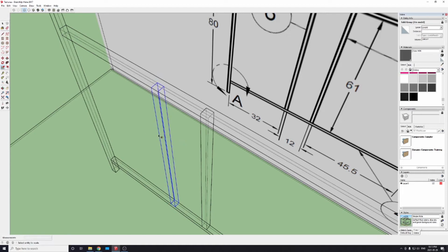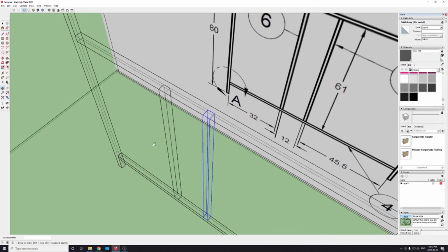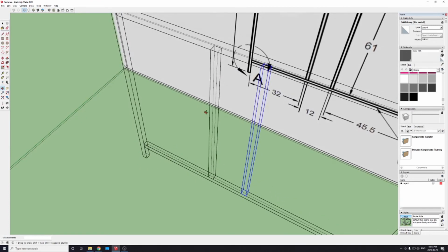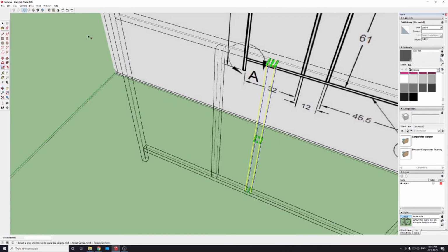Okay, so then we're going to left click, select this object. Might have to pick the edge itself. S to scale, pick the middle piece, and now I can use this same piece here, this corner, or we can go back to here, either one, and left click again. And that should make our pieces the same height as our horizontals.